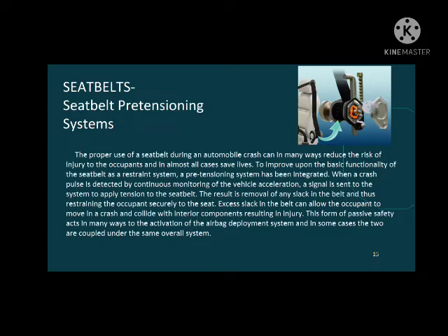The electric pre-tensioner replaces the pendulum with an electrical sensor. This prevents the false locking condition that is commonly observed with the mechanical pre-tensioner. The electrical sensor can also be interconnected with other systems on the vehicle, such as the rollover sensor or airbag sensor. This connectivity ensures that the seat belts will lock even if the sudden deceleration that is needed to lock a mechanical pre-tensioner does not occur.